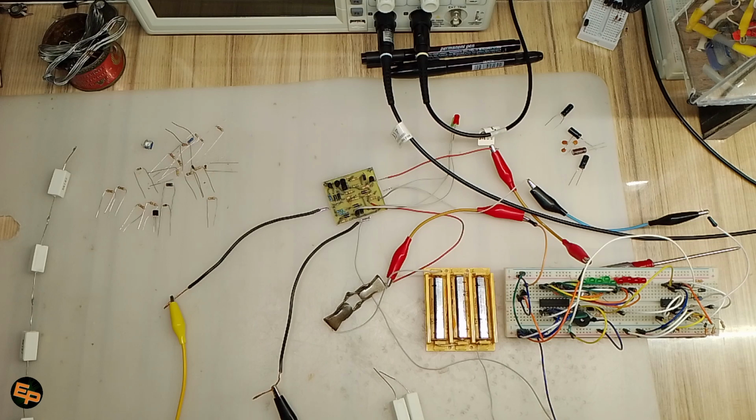this interference would appear in this wire, and it would make it so that the ground of the breadboard circuit would not be exactly the same as the ground on the PCB, and therefore this entire circuit on the breadboard was functioning in a different way. Okay, and I was connecting something on the outside of the screen, but I was connecting the same thing every time.